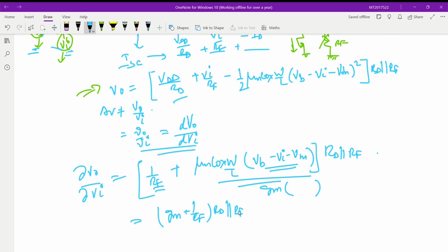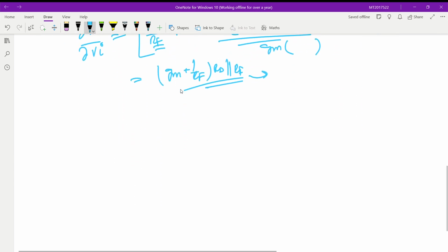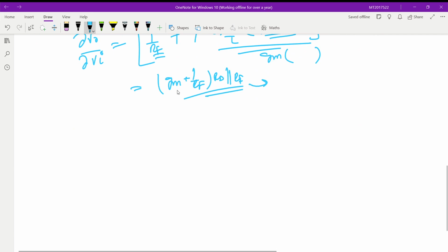This must be a very similar result, right? This is a similar result. If we use a small signal analysis, we'll find out this number. But what is the basis for that number? So we have gone through this. Okay, this is a positive gain. That means if Vin increases, Vout will also increase along with that.